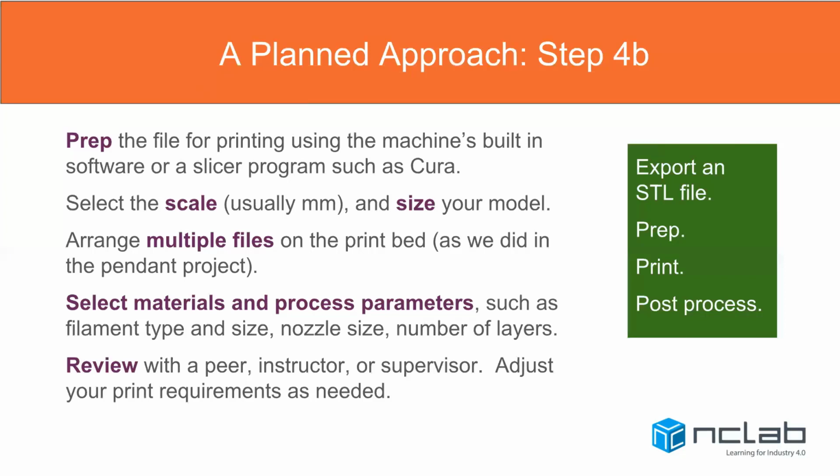You're going to select the materials and the process parameters: what type of filament, type and size, maybe even color, and so forth. And then once again, review it before you send it. You might save a lot of grief.